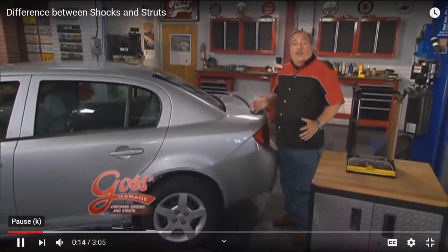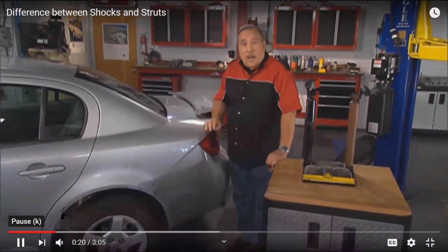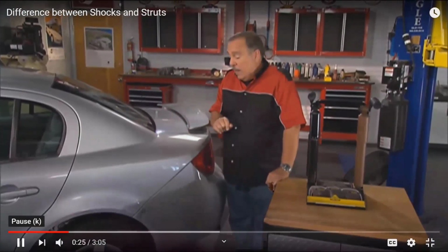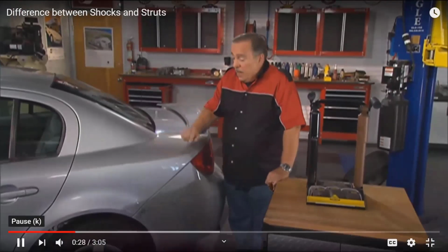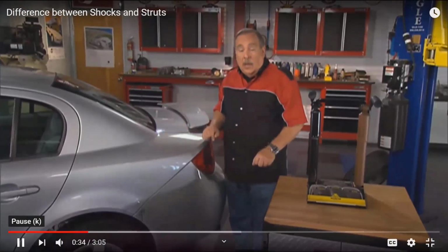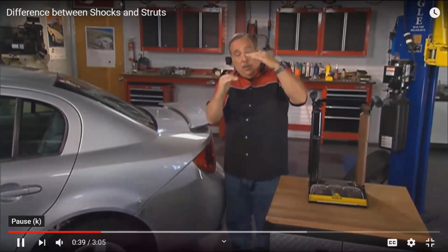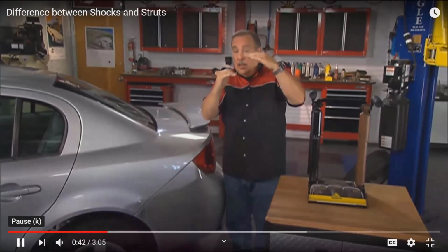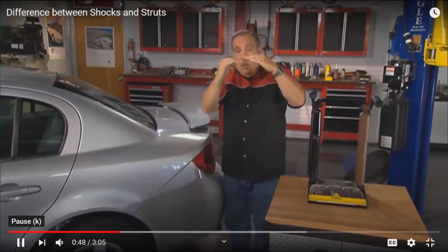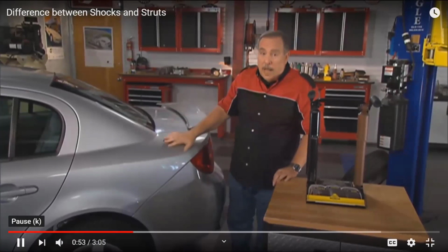A car that bounces as you go down the road can be very tiring and very annoying. And keeping it from bouncing is the job of the shock absorbers or the struts, whichever your car happens to have. Now, the way you test them is a couple times a year. You go around each corner of the car and bounce it up and down like I did this one. And what's going to happen is it's going to go like this. You let go of it in the down position, and if the shock or strut on that corner of the car is good, it'll come back to the center and it will stop. It won't continue to bounce. If it continues to bounce, probably you need new shocks or struts.